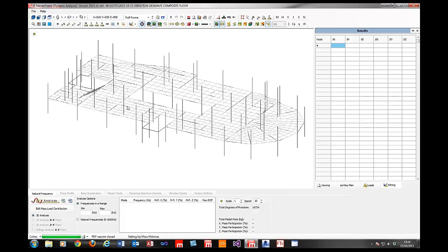If this were a plain floor without the columns, we would actually have had the option to analyze it as a grillage, hence using 3 degrees of freedom per node and not 6, and that would cut down your analysis a little bit more, which is particularly helpful if it's a really, really large floor plate and you haven't introduced the columns in the modeling.